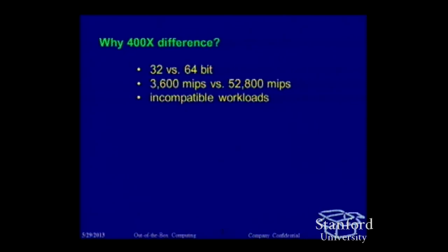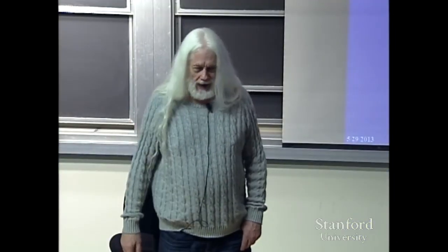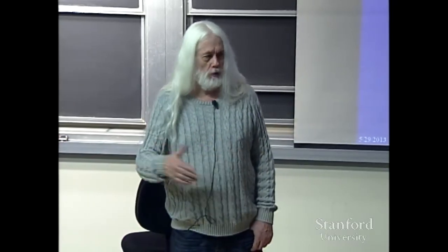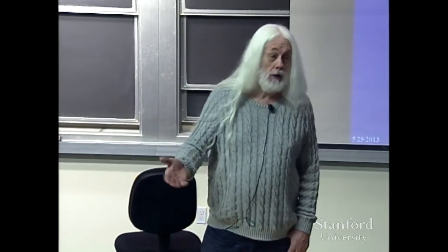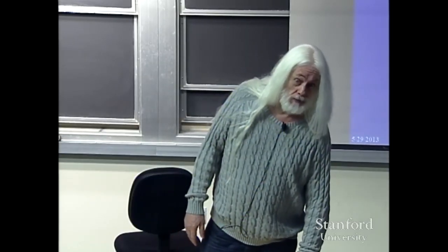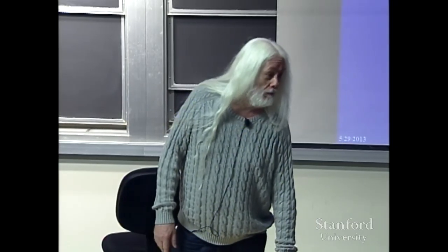The TI chip running on a general purpose workload is truly awful. It is designed for things which stay in loops forever, software pipeline loops. Code that is just full of random flow of control and random memory references, which is characteristic of your general purpose code, it tends to be very bad on. Now, the Intel chip would make a fairly decent DSP if you could buy enough Freon.